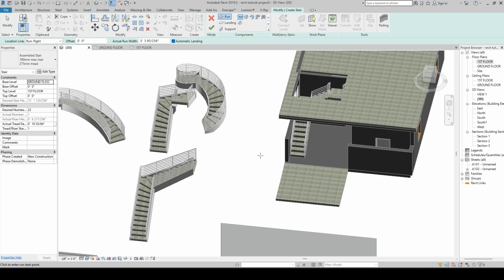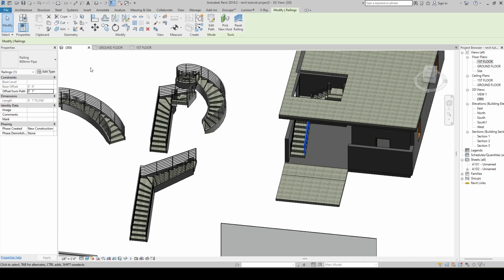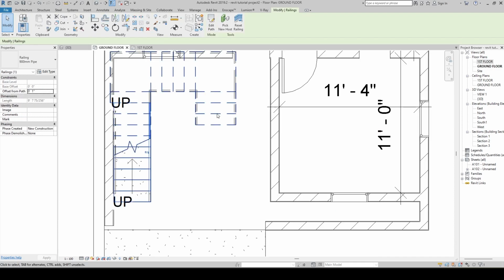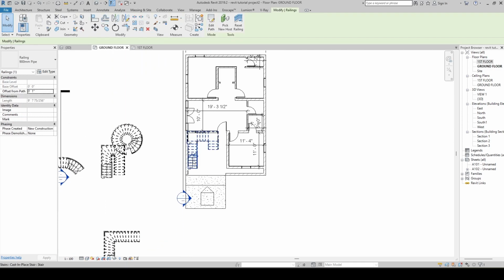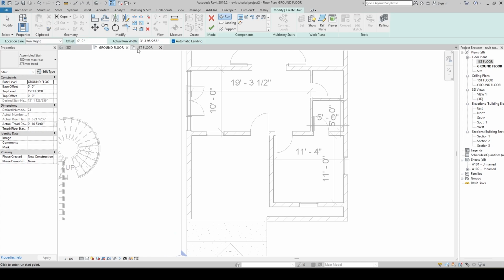So in order to explore this, let me exit first. Let me go to the ground floor. I delete this first. Okay, I delete the staircase. Okay, so now I'll go to the staircase. I'm just in the ground floor. Now the width of the staircase I'll enter as 3 feet. Okay, now I'll take the create sketch.